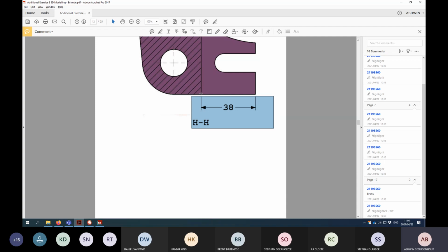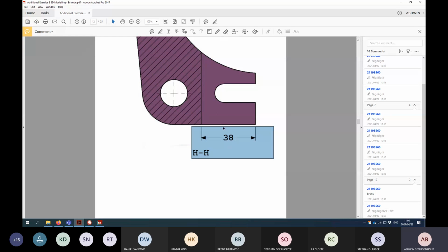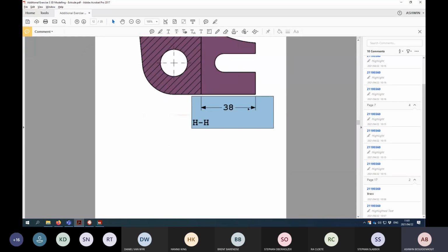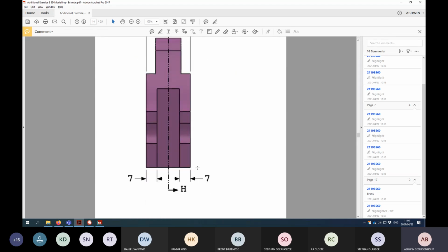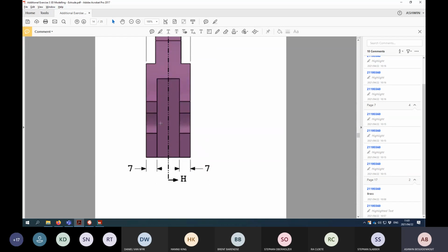So I'm going to use this bottom face, and then I'm just going to extrude everything upwards. You can extrude it upwards, you can extrude it downwards, you can extrude it from this side. But because I can incorporate all of these dimensions within one sketch, if I need to change something, I have one sketch that I have to go and change. Okay. So, and then I can use extrude, cut, all through all to basically just do the rest.